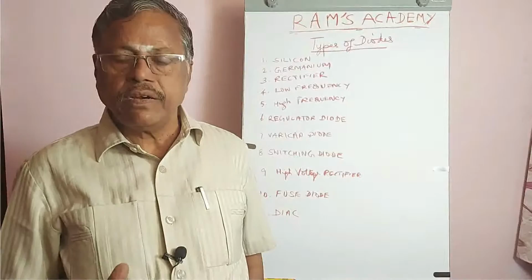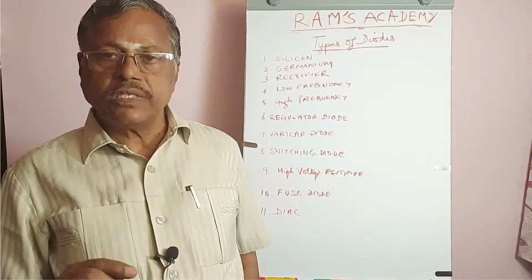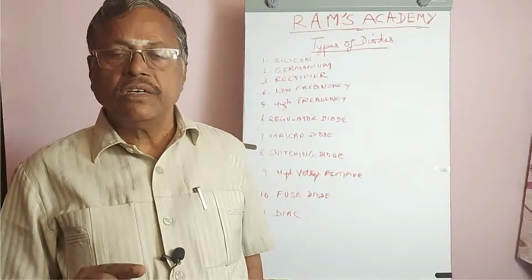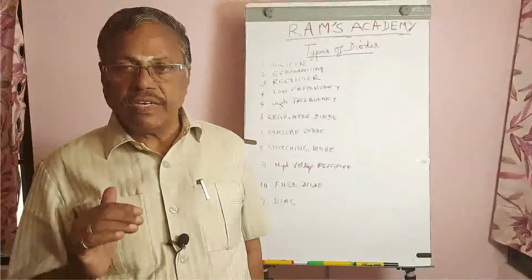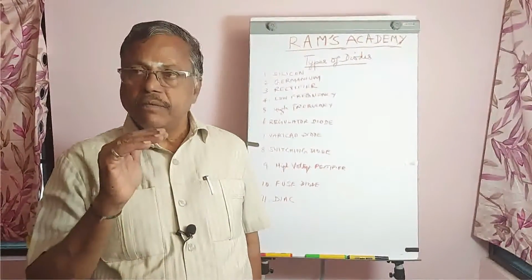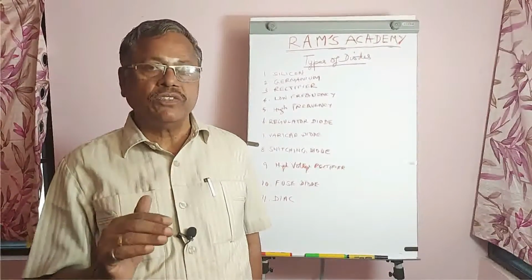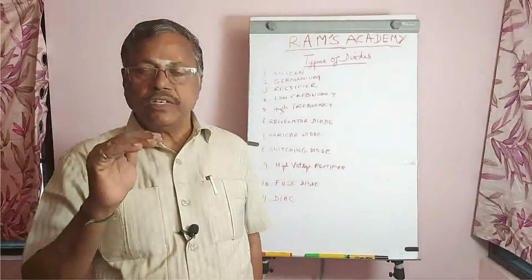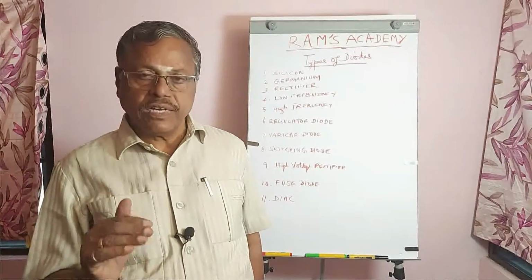When they are liberated, what happens? If we have another electrode just above the cathode, and we give it a positive potential with respect to the cathode, then since the electrons have negative charge and the top electrode has a positive charge, they are attracted and electrons start moving towards the anode terminal. The bottom one, which is heated, is called the cathode.